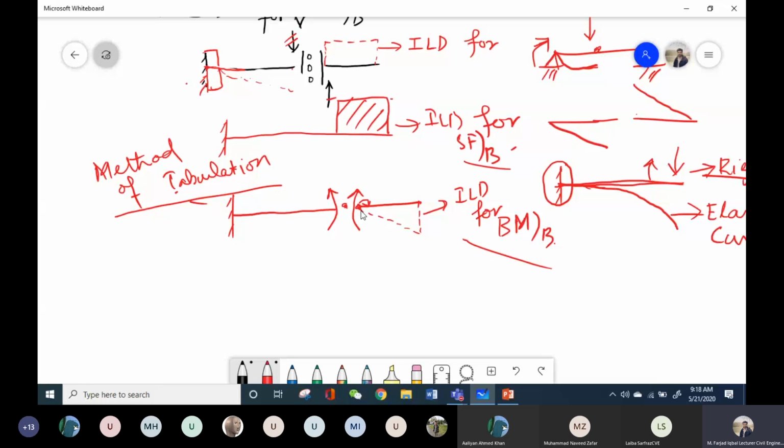We also discussed this in the last lecture, but again I will repeat. For the case of bending moment, how is the bending moment actually applied on a member? You usually hold this beam from this point, and then you try to apply the rotation in the clockwise direction. Let's say just next to this point, and just physically, if you have any pen or pencil in your hand, just hold this pencil at one end and try to rotate it in the clockwise direction, and just look at in which direction it is going to rotate, or what is its deflected shape.